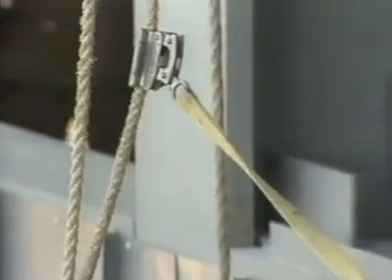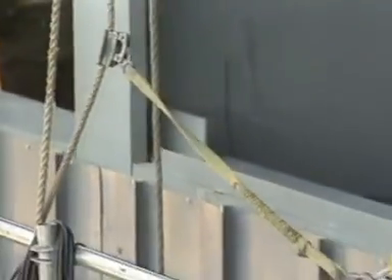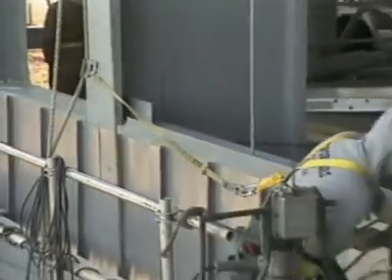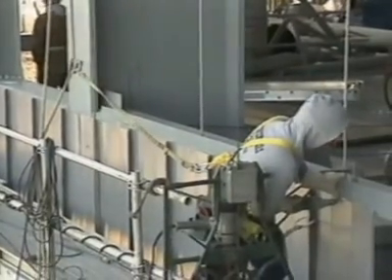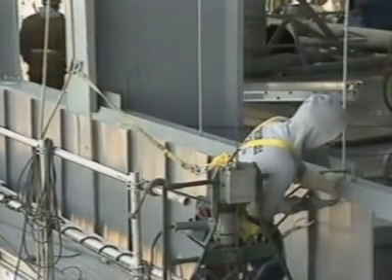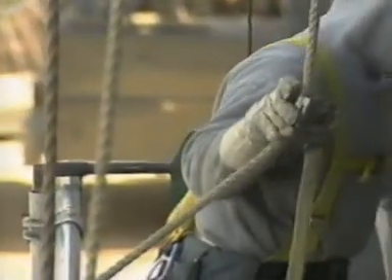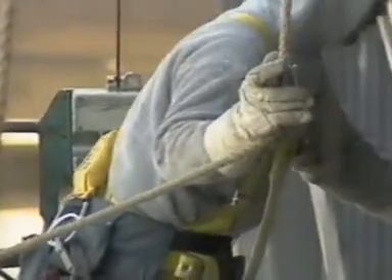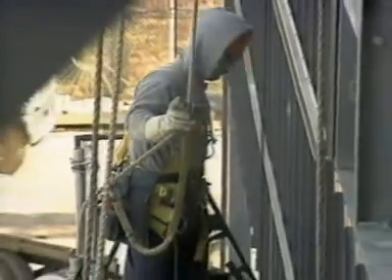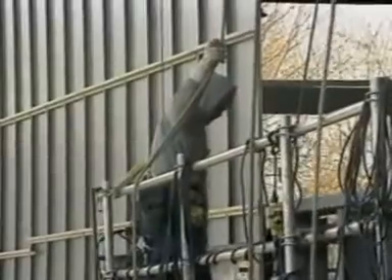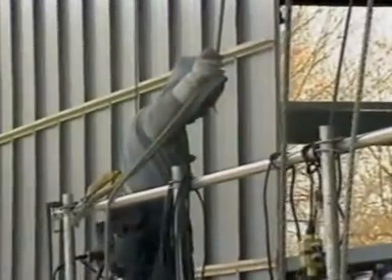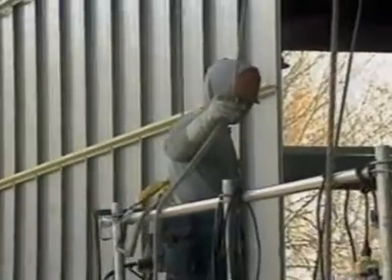It's vitally important that everyone who is required to work on any type of scaffold with a platform more than 6 feet above the surface must wear a safety harness and lanyard. The lanyard must be fastened to either a structural member or a securely rigged lifeline that will safely support the worker if he or the scaffold itself should fall. For obvious reasons, the lanyard must never be attached directly to the scaffold, and if it's not attached to anything, it certainly won't help.